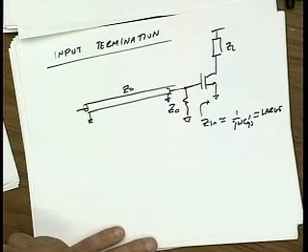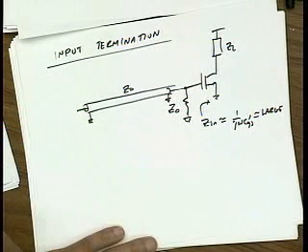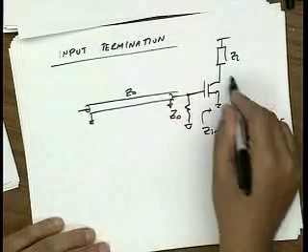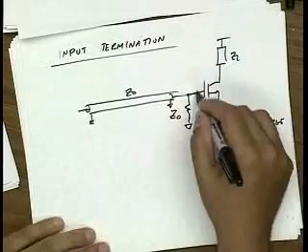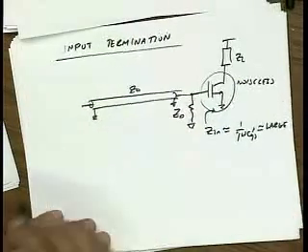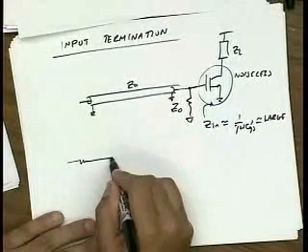Yeah, the additional noise of the resistor, probably. How much does that noise really hurt us? It's a factor of 2, right? Yeah, it's a factor of 2, because if I now ignore the noise, let me assume that this transistor is noiseless, then I have an equivalent circuit that looks like this.